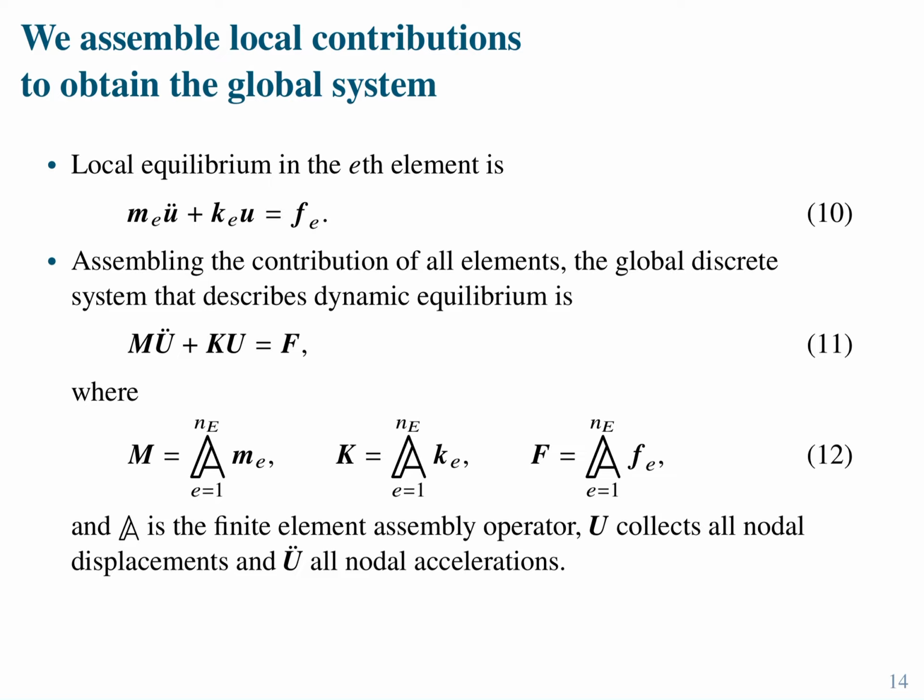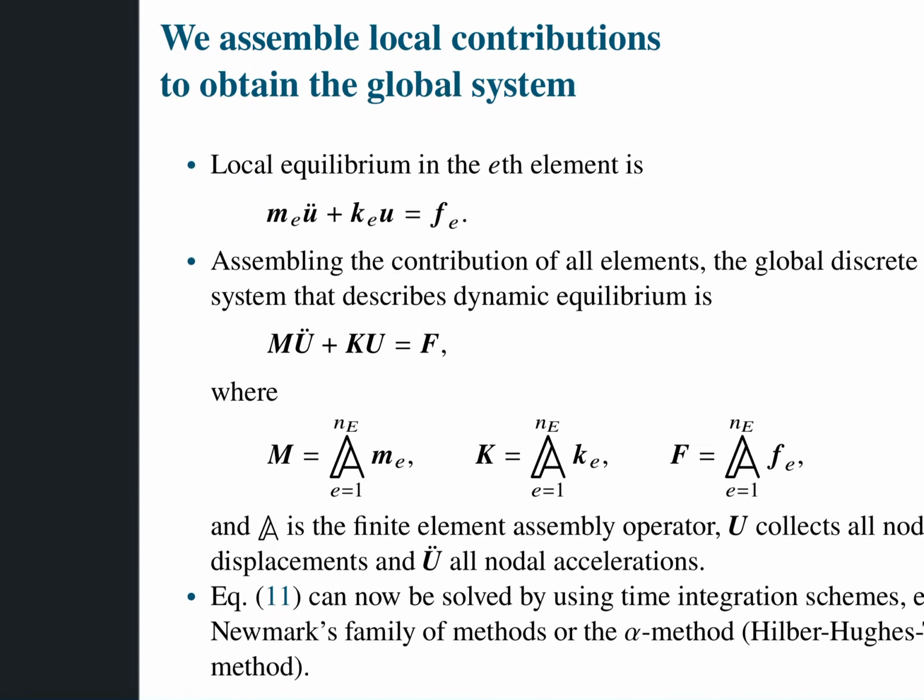So the idea is that when you have your stiffness matrix at the element level, you complement that with the so-called element freedom table, which is basically telling you how you're going to map those coefficients in the matrices into the global system. That's all it is. It's the standard finite element assembly operator that we normally write in books and papers. But again, it's simply a matter of having proper additions so that our system is properly set.